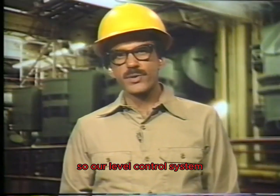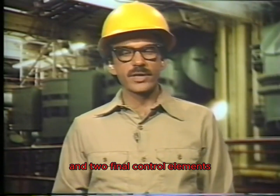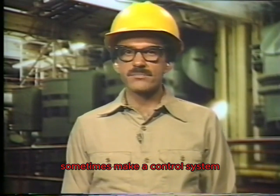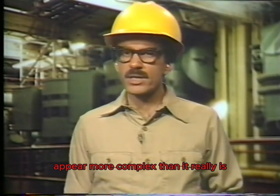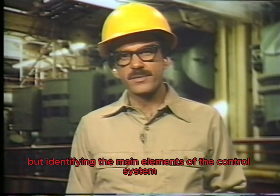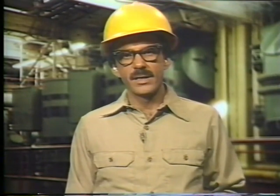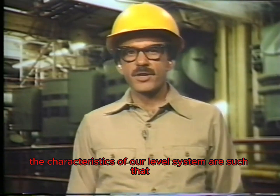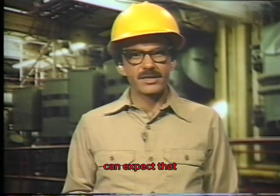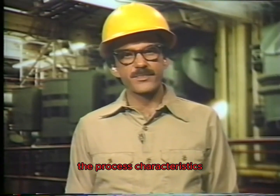So our level control system example has two controlling elements and two final control elements. Additional control elements can sometimes make a control system appear more complex than it really is. But identifying the main elements of the control system and what they do make it easier to understand the system. Now, the characteristics of our level system are such that level changes slowly, and we can expect that the controllers are adjusted to compensate for the process characteristics.